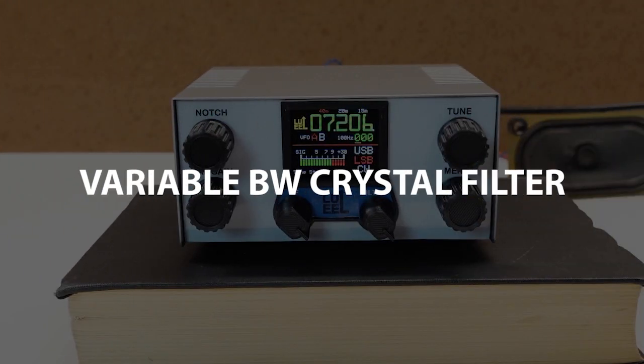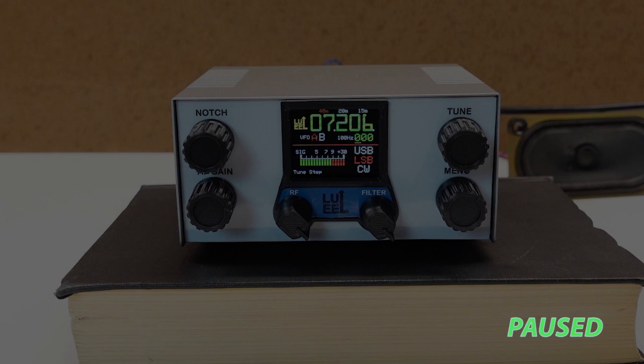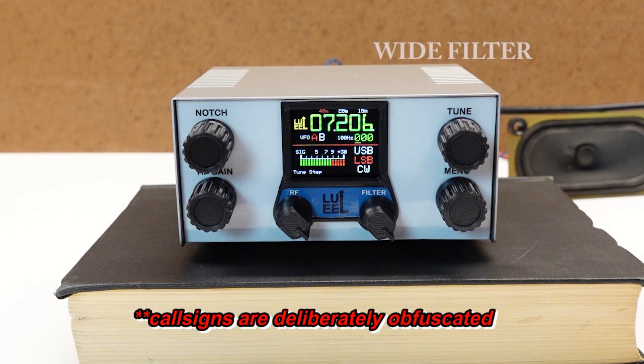In this demo is how to use the variable bandwidth crystal filter to reduce interfering single sideband signals. In this case, I'm trying to listen to this ham working the Michigan QSO party. There's another fellow transmitting up frequency. His signal sounds like a very high-pitched squeak. Listen now as I narrow the filter to knock down the squeak.